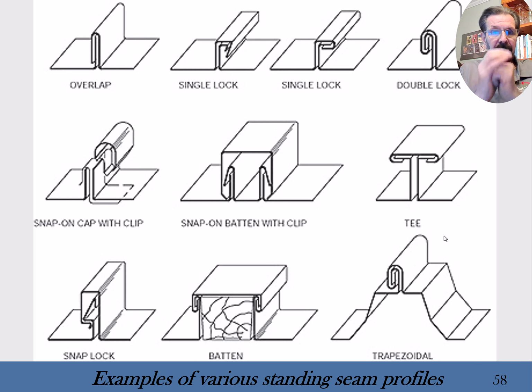You try to have the seam standing up in the air so that the water's not going to collect where the seam is at, and that's how a standing seam works to keep the water out, by standing up in the air, so the water's going to end up in the valley and it's not going to end up at the top of the peak, because it's not hanging around long enough for that.